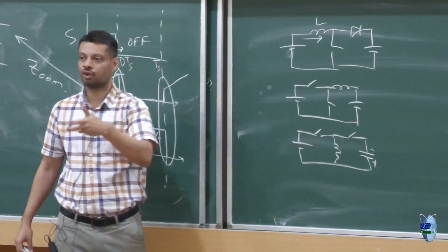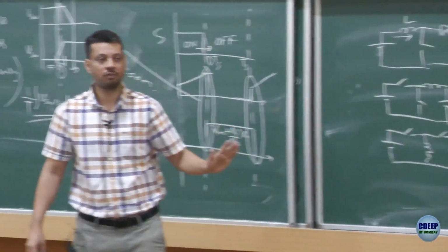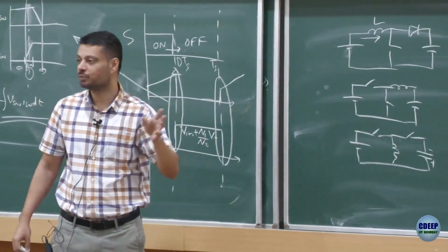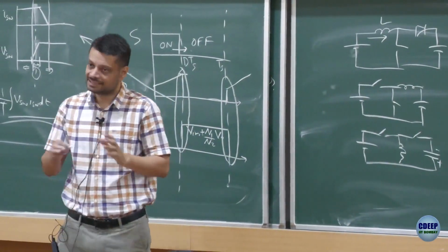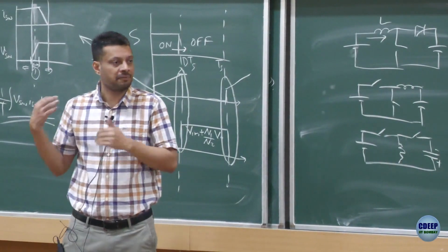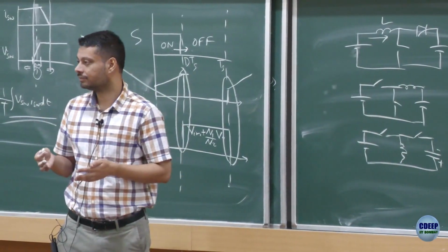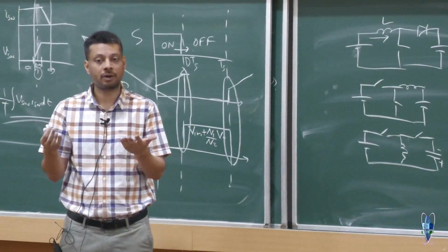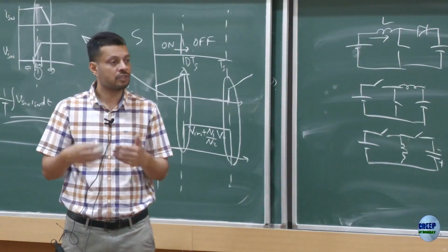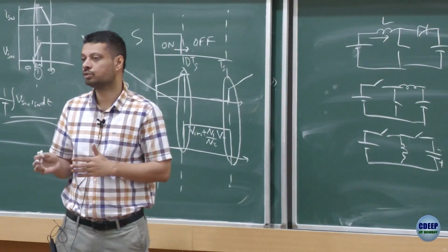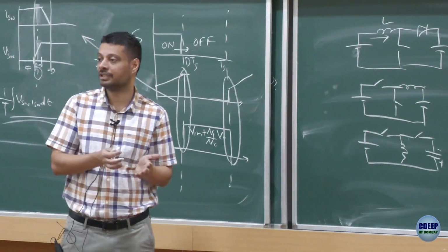So if your choice is that you always have to boost, you go with boost. You don't go with buck boost. And that's the same reason. If you remember, the flyback is like a buck boost circuit, right? If you can always operate in boost, or you can always operate in buck, you should not use flyback then. You can use some other topology, right?